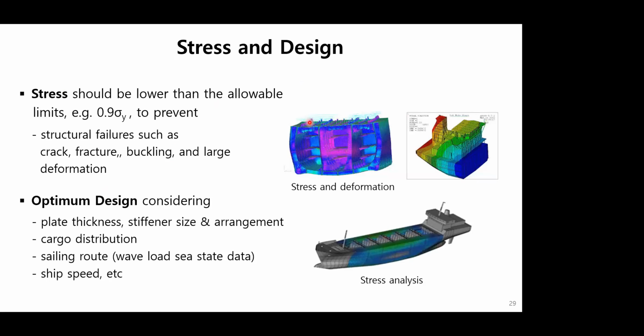In actual design, the stress should be lower than about 90% of yield stress to prevent structural failures such as crack and fracture. For this purpose, very tedious and complicated finite element analyses are often carried out in the initial and later design stages. Sometimes stresses should be much less than yield stress in order to prevent buckling and large deformation.